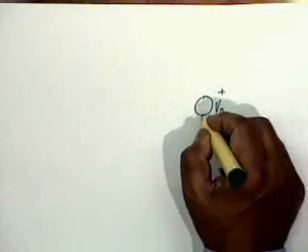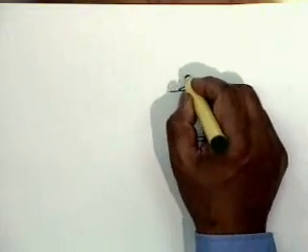The rest of the analysis you can do yourself. R out calculation is not trivial. For R out, you have to apply a voltage source and find the current. Let me draw the circuit.